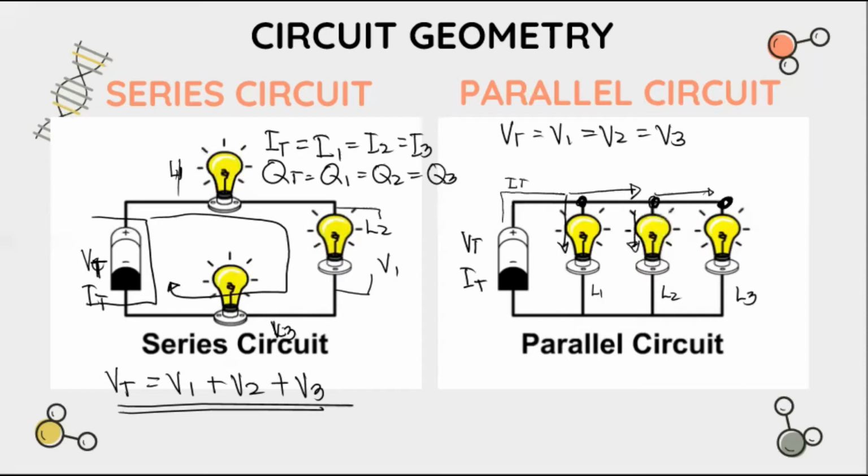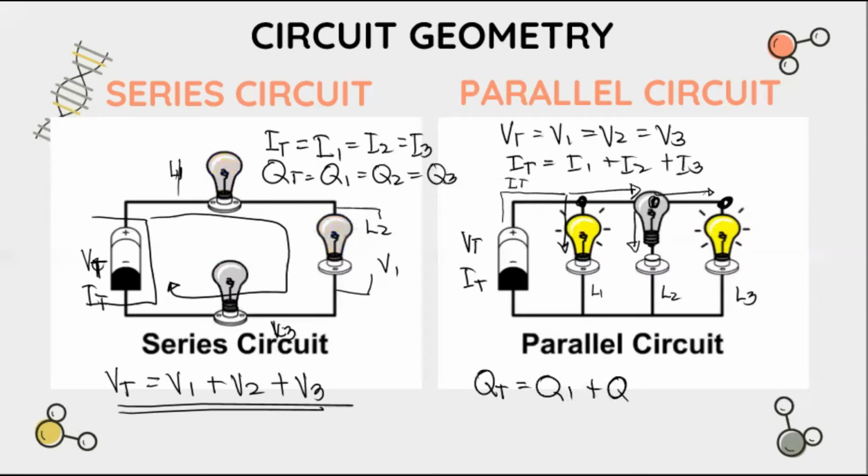Okay? So, meaning, yung IT natin, or yung total current natin would not be the same in each component. Okay, so kapag parallel, IT is equals to current sa 1 plus current sa 2 plus current sa 3. Okay? So, since current is directly proportional with our charges, QT is equals to Q1 plus Q2 plus Q3. Okay? So, tandaan po natin itong concept na to.